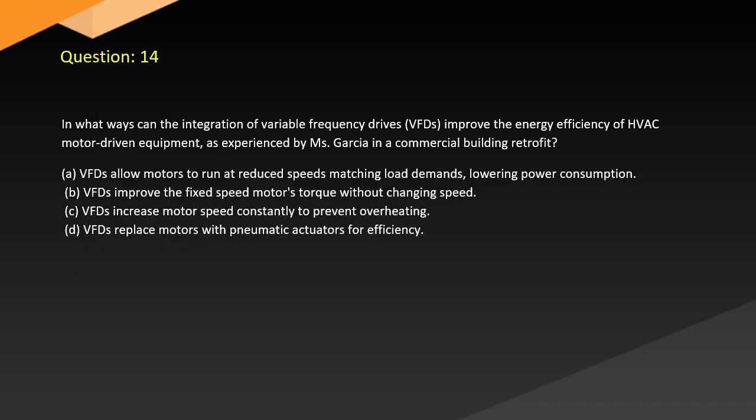Question 14. In what ways can the integration of variable frequency drives (VFDs) improve the energy efficiency of HVAC motor-driven equipment as experienced by HVACR engineers in a commercial building retrofit? A. The VFDs allow motors to run at reduced speeds, matching load demands, lowering power consumption. B. VFDs improve the fixed-speed motor's torque without changing speed. C. VFDs increase motor speed constantly to prevent overheating. D. VFDs replace motors with pneumatic actuators for efficiency.